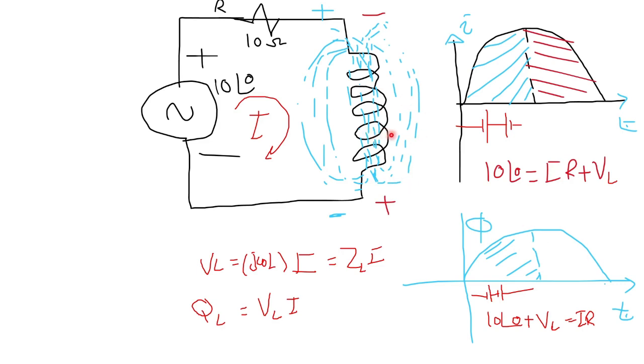The amount of energy stored in the coil in the form of a magnetic field will depend on the rate of change of the current generating it. Rate of change meaning the current must be changing first. A DC current passing through the coil would not cause any energy to be stored. The coil would act like a short circuit. But a changing current would cause the coil to store energy in the form of magnetic flux.